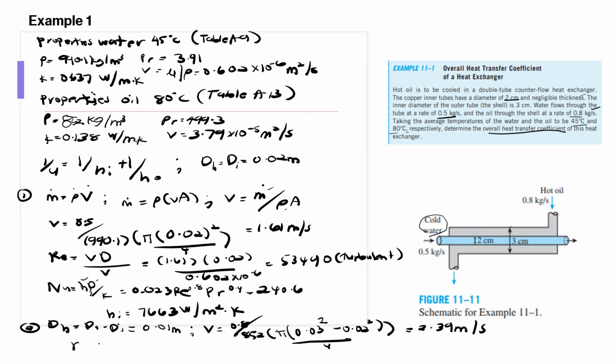So the Reynolds number formula V D over nu. So please remember this one. If you need to calculate the area for the annular space, you need to put in the Dh formula. This part. So now for the Reynolds V D over nu, in here you can directly put the Dh value, which is 0.01.